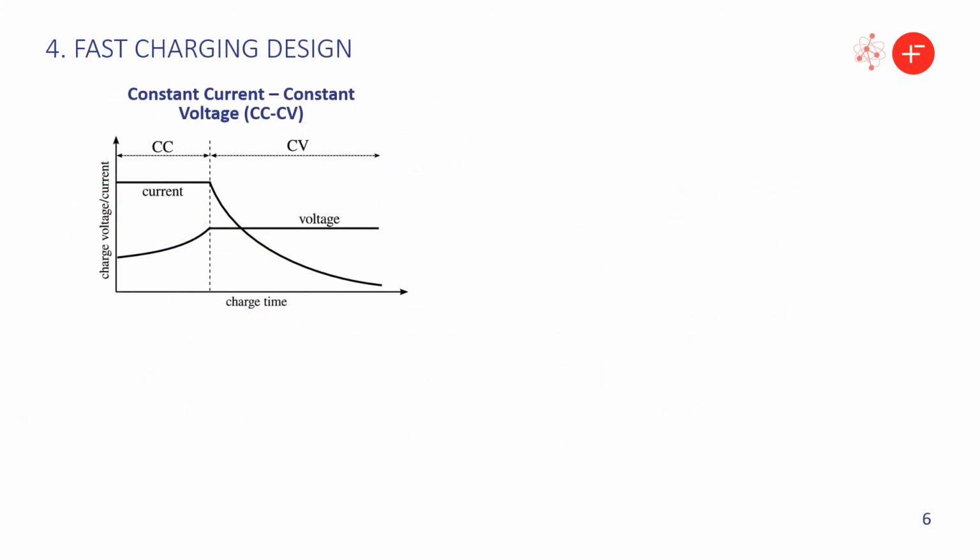The charging controller is designed with fast charging strategies. The traditional method is CCCV, which I have introduced before. It is widely used, but has plenty of issues in fast charge. The most significant issues are lithium plating and high cell temperature if applying high charging current.